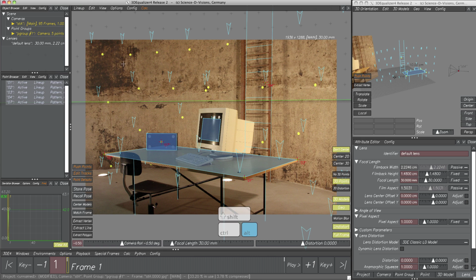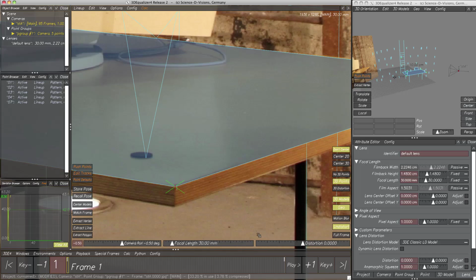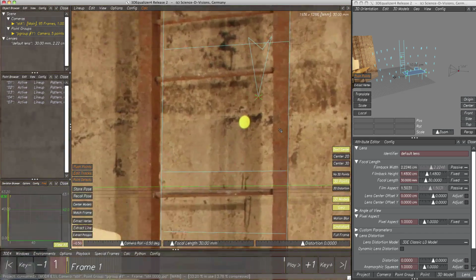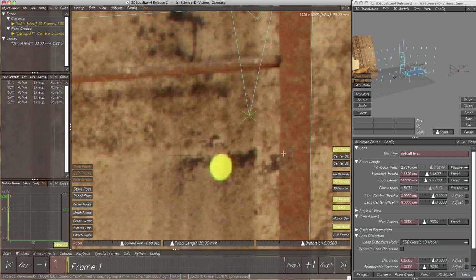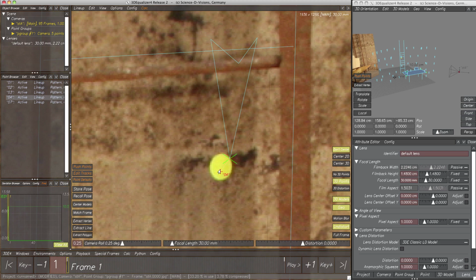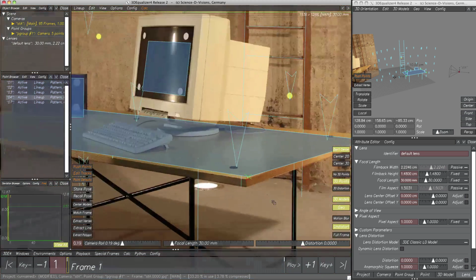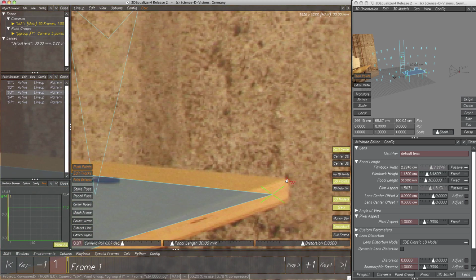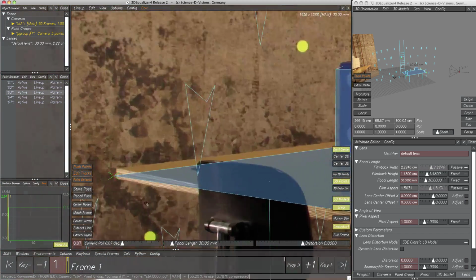As I mentioned previously, a false focal length and distortion value might cause the incorrect alignment. The differences of the alignment's accuracy between the table and the locators on the wall indicate this. In the next few steps, we will adjust focal length and distortion to enhance the alignment drastically. But first, we have to make sure that every 2D tracking point is placed on its respective feature as precisely as possible, having a correct tracking for starting the adjustment.